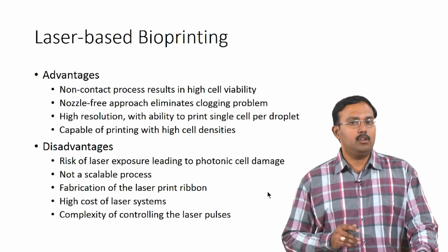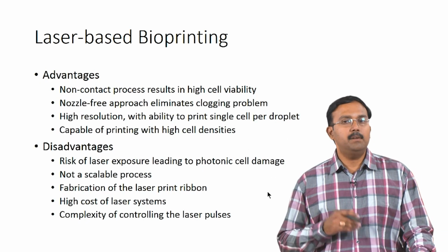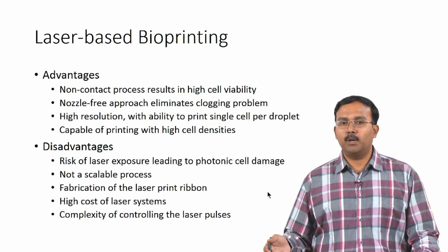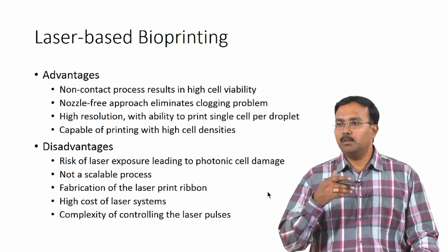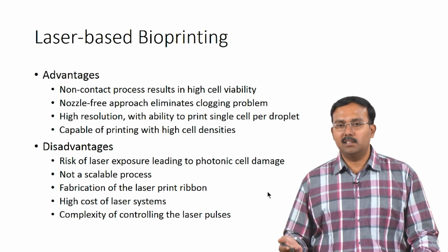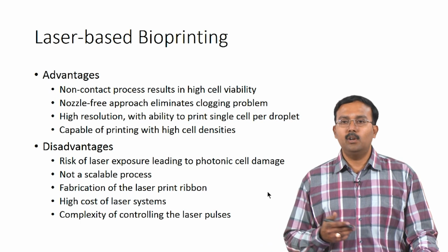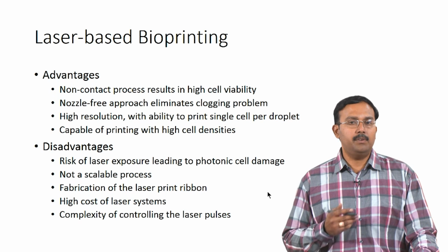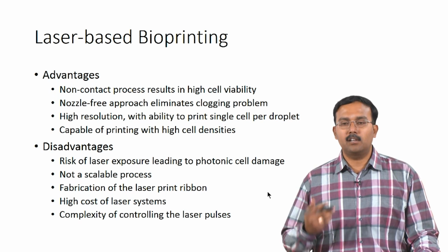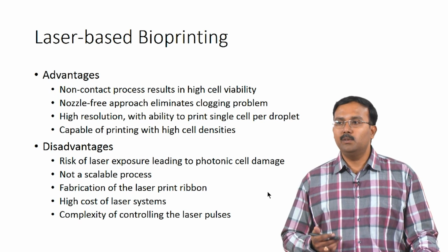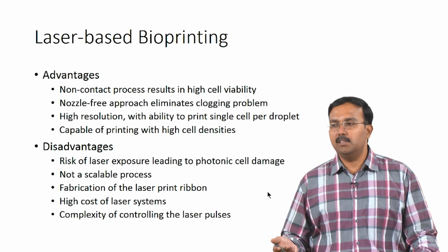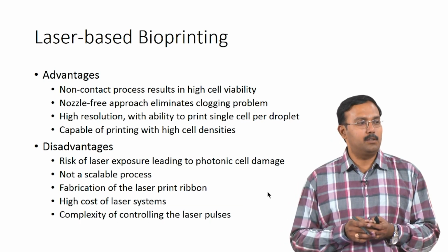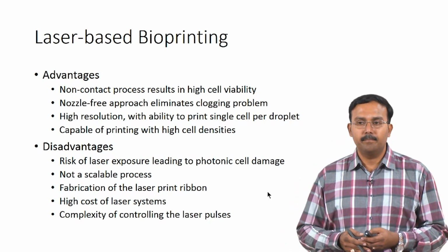The advantage is it is a non-contact process, which means there can be very high cell viability. When you have a shear process, like when you have a nozzle, cells have to go through shear, which can actually cause cell destruction. Here you do not have that kind of shear stress. The nozzle free approach also eliminates the clogging problem, so you can use material which is very highly viscous. That could be an advantage, because once it is printed, it could form a gel very quickly.